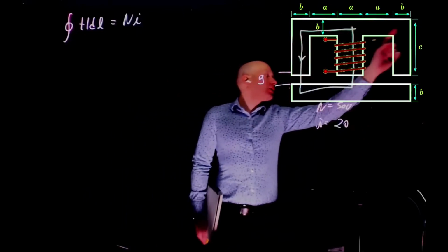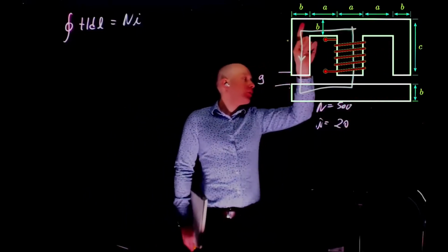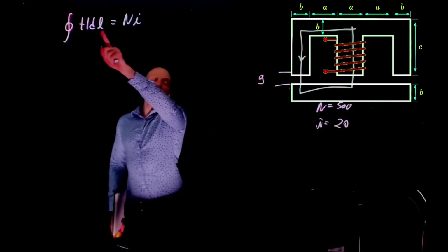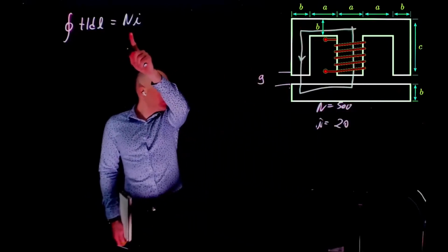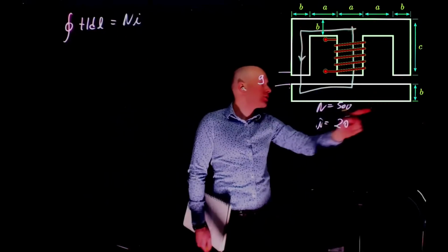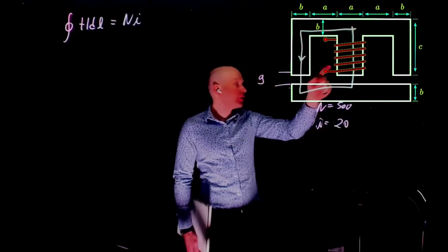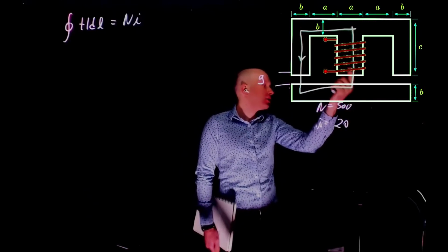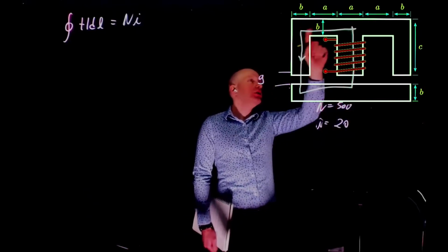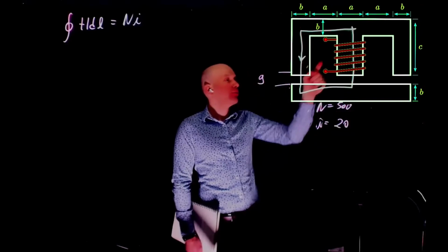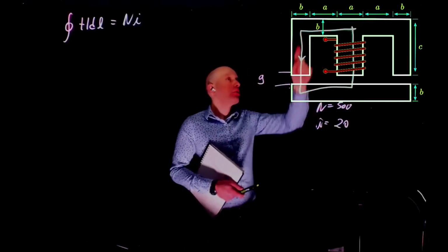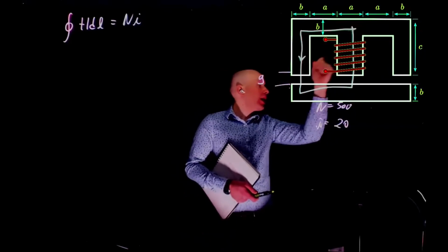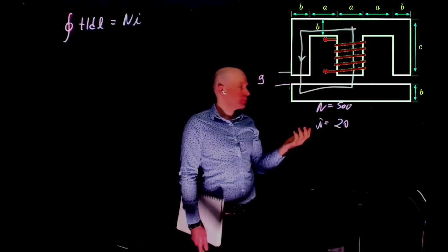We cannot select this path. Why? If you take the outer loop here, the integral of H dl will be 0, because there's no current going through the surface, through the path. Everything is looping inside there. So we need the current to be flowing in. If our path goes all the way there, then the current flows in and out, and they cancel out, right?